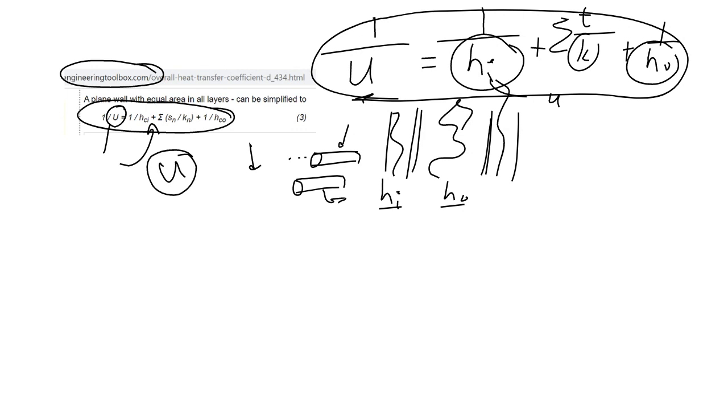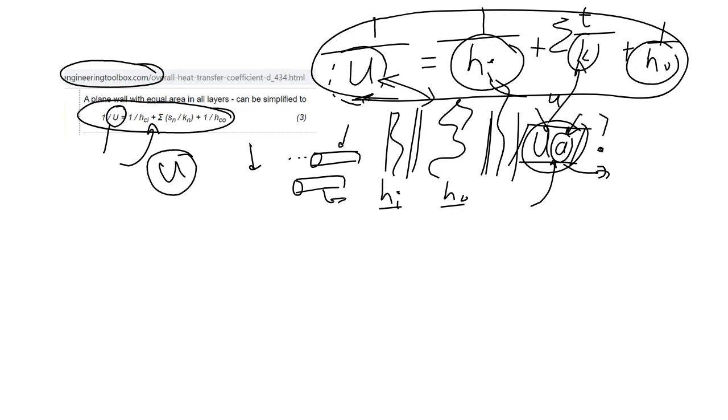Okay, right. But this is what I want you to, maybe not necessarily for the assignment, depending once again on your capacity and how much detail you want to think about this: question 2 that says, is this UA value realistic? It wants you just to consider these aspects. And you can spend days on it, I know. But just as a preemptive measure to make you aware: it is not for all designs. It's not the values that Elizabeth gave in the tuts. It is dependent on how you design your reactor, and it is dependent on the material of construction, flow rates, what the fluid is, the viscosity, the linear velocity inside your tube, and the viscosity of the type of fluid that you have on the outside, on the shell side of your heat exchanger. That's typically what you will have to consider. Right, so questions on this?